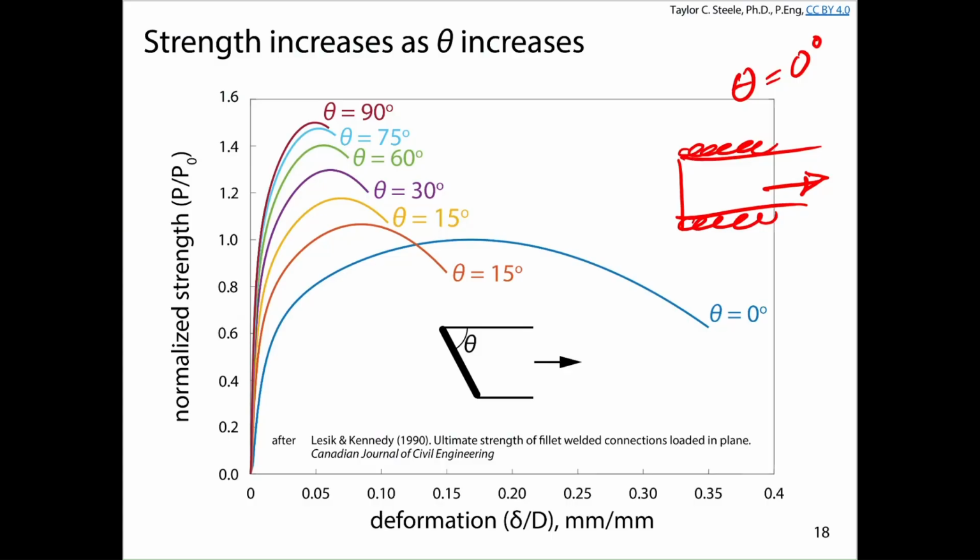And when we have welds loaded in shear, as I mentioned in lecture 2 for this course, the failure of steel in shear is very ductile. And so we get a response something like this. We reach the ultimate strength somewhere out here, off towards a failure strain where we get fracture of the weld. Okay, so welds, when they're loaded in shear, are very ductile.